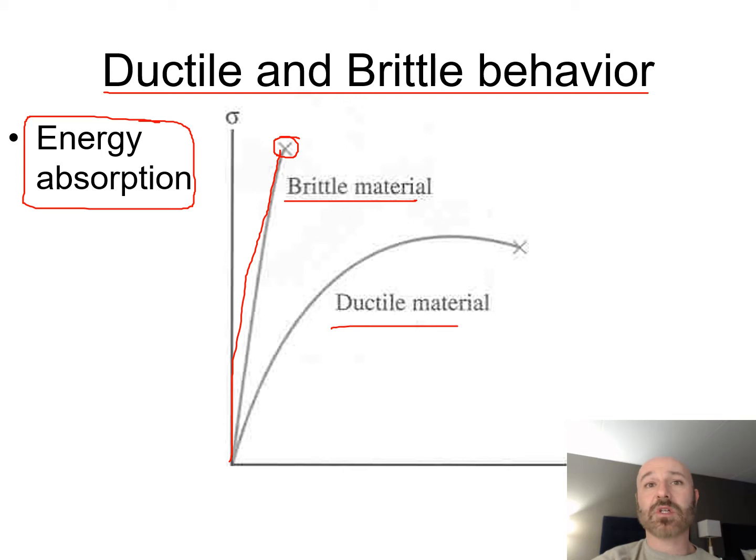Whereas we see a more ductile material, we have a more soft curve like this here, where we can see there's not much of a linear region here. It gets into the plastic region, then you have your strain hardening, then you have your ultimate strength, then you have your necking, and then you have failure at the end there for more ductile materials. This is something more of a steel as compared to an aluminum or a plastic down here.